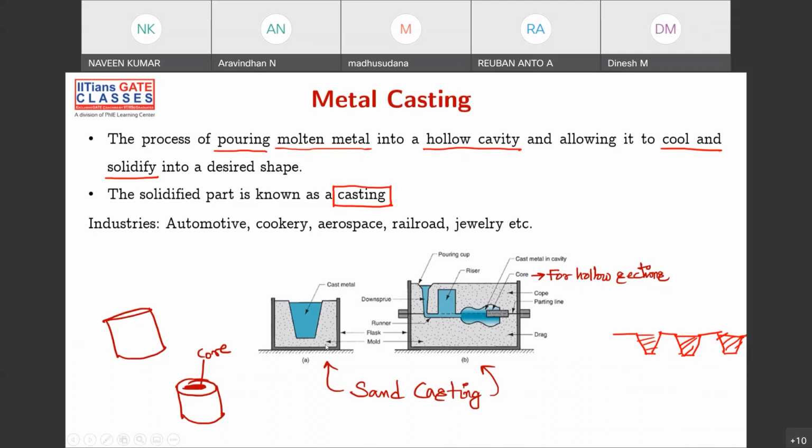So this is called your mold, this is called your flask, this is your runner, this is the down sprue, this is your riser. All these things are known as gating elements. We'll be discussing this figure in detail when we're discussing the gating elements. Here I have put this diagram because it's not as easy as it's looking. You can't directly pour. You have to have some setup, because through that setup we'll be able to pour material at the right time, and then we'll be able to properly solidify it so that we can get the desired properties. Okay, fine. Let's move on.